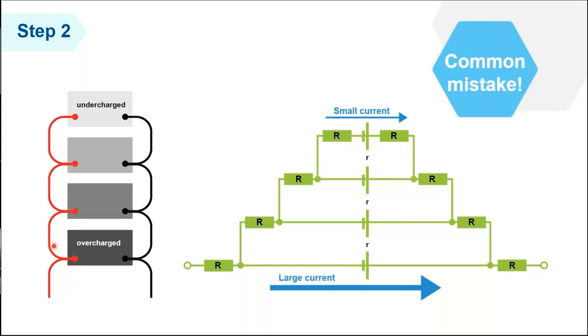The power coming from the bottom battery will travel through the main connection leads. So it's seeing this kind of resistance. If you consider these are the cables, and the cables have their own resistance, and these are the leads, and the resistance of the batteries itself is R, and the resistance of the cables is the capital R, then the power coming from this battery only travels through the main connection leads. However, the power from this battery has to travel through the main connections and the 2 interconnecting leads to the next battery. And this is the case for the next batteries. The next battery has to go through 4 sets of interconnections. The other one has to go through 3 of 6 interconnections.